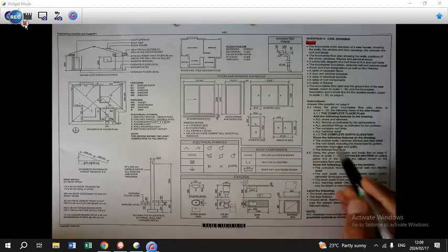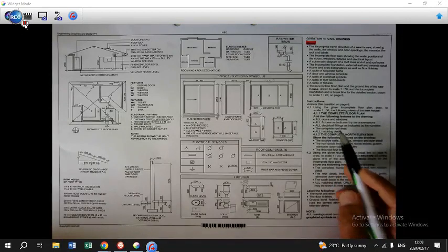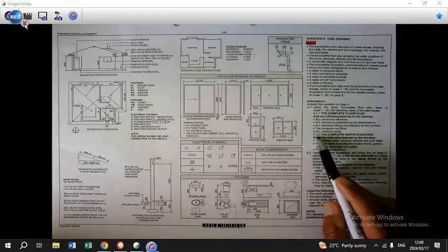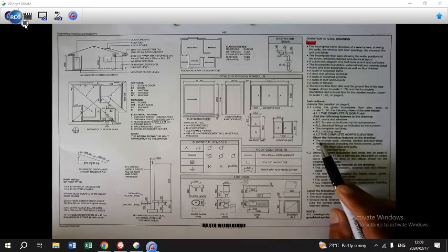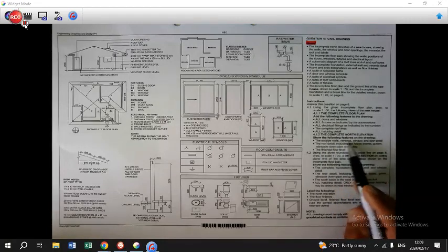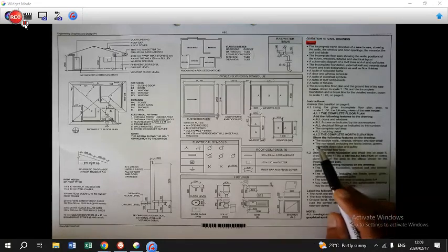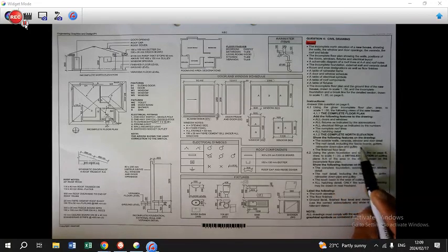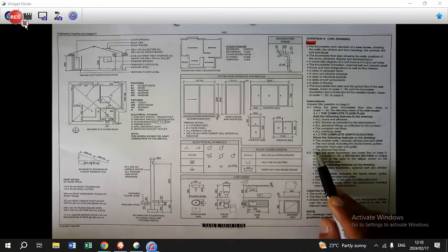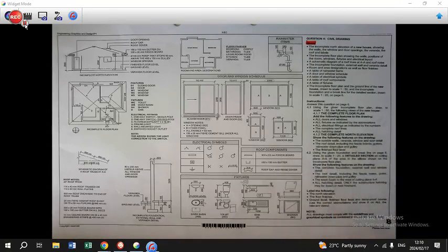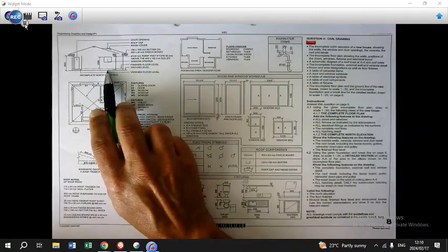So if you look at those instructions, you are going to continue with a scale of 1:50. 4.1.2, you have to complete the north elevation by showing the following features on the drawing: the outside walls, veranda, window and door detail, the roof detail including the fascia boards, gutters, rainwater downpipe and gully. And then of course finally you have to do the finished floor level as well, which is on the inside of the house, which you are going to see there.